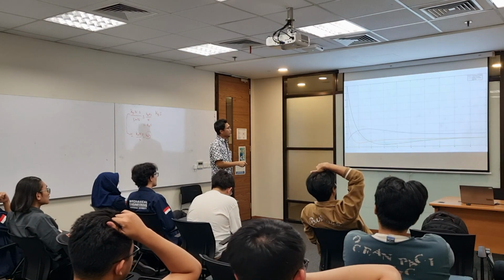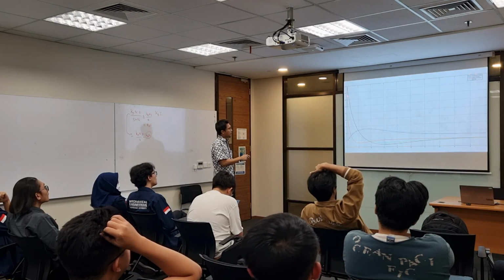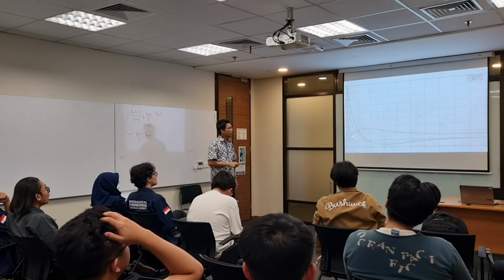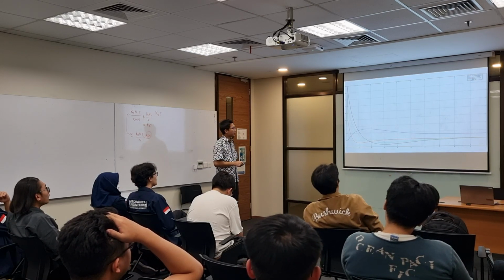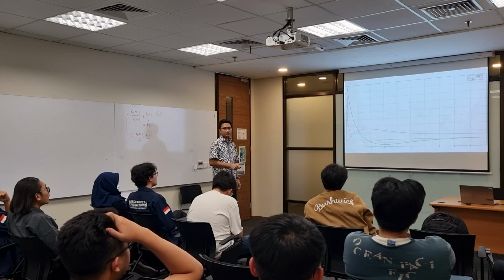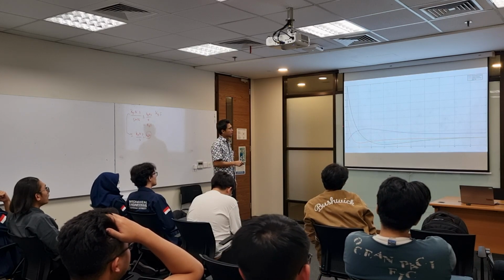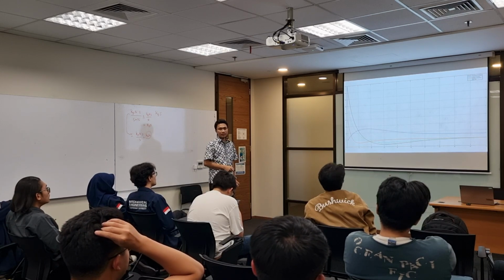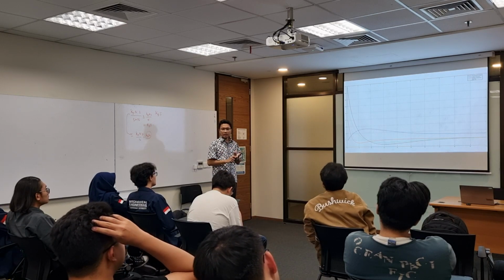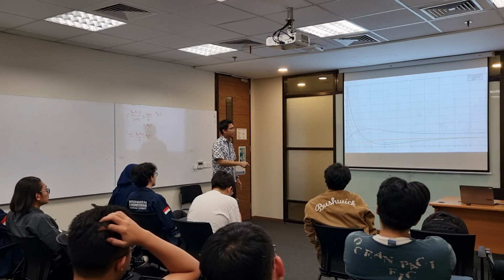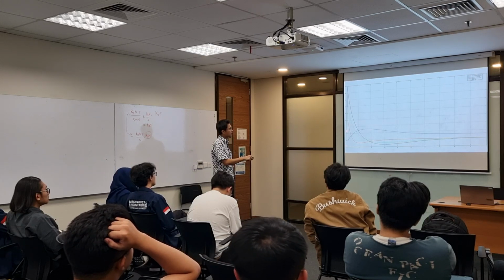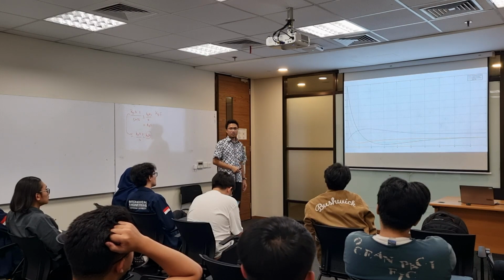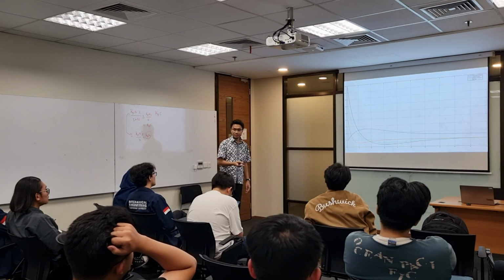Okay. So what you see here is that the black one is the proportional control action, the blue one is the integral, and the red one is the derivative. The dashed green line is the error. Proportional control tries to follow the error proportionally, as you can see. When the error is large, it's large, and when it is small, it's small, and when the error is 0, the control action from proportional is 0.